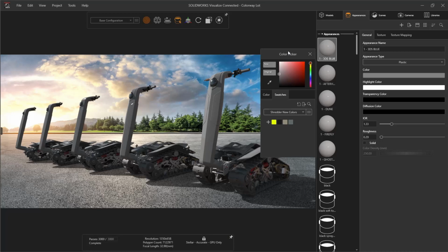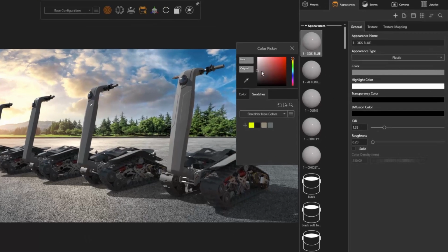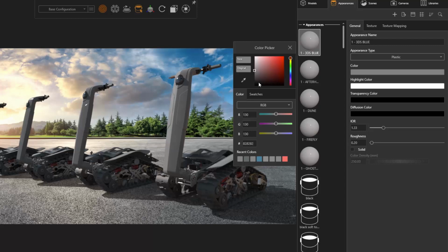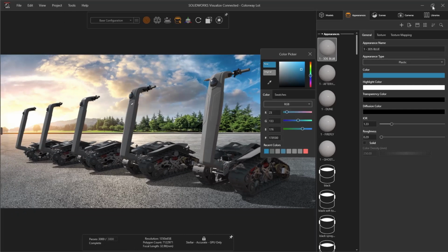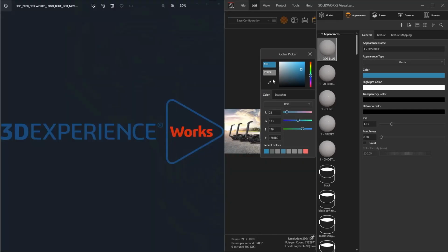In cases where the colours are not available to be imported, they can be added in a similar fashion to previous releases. On the Colour tab, colour can be selected with the graphical display, and the hue slider is now present in RGB as well as HSV. The ability to simply paste in a hex code has now also been added, as well as CMYK definition for print applications. As always, the colour picker itself can be used to select a value anywhere on screen, and its colour preview has now been enlarged for greater accuracy while selecting.